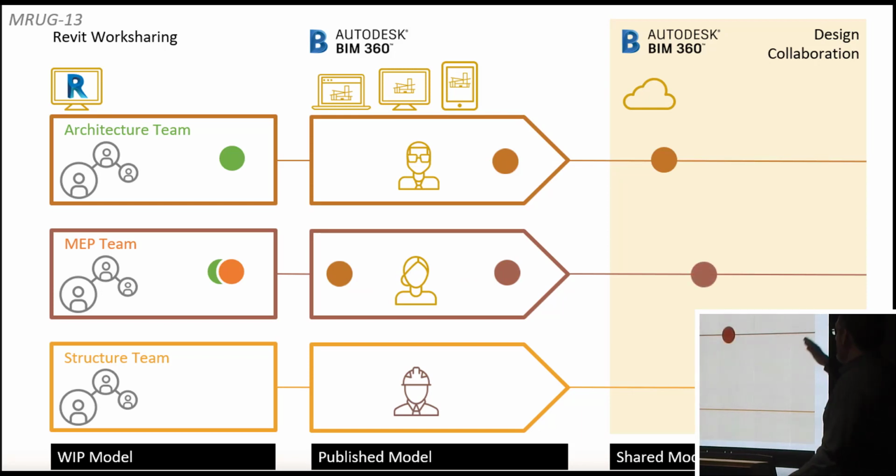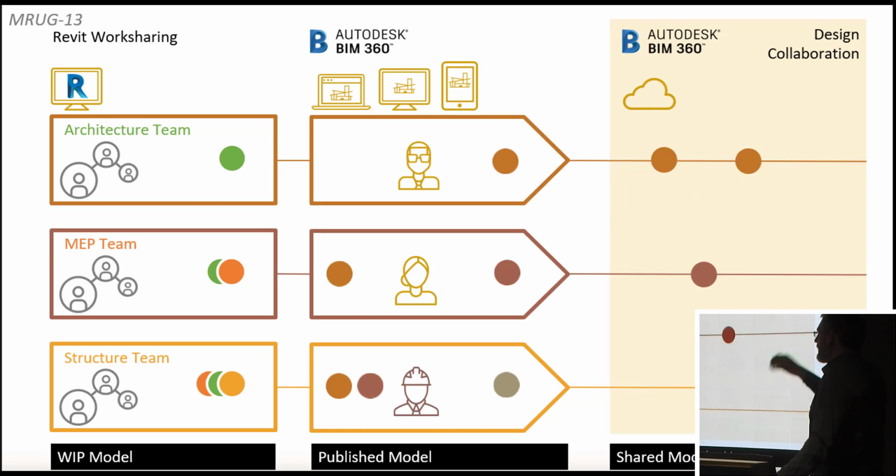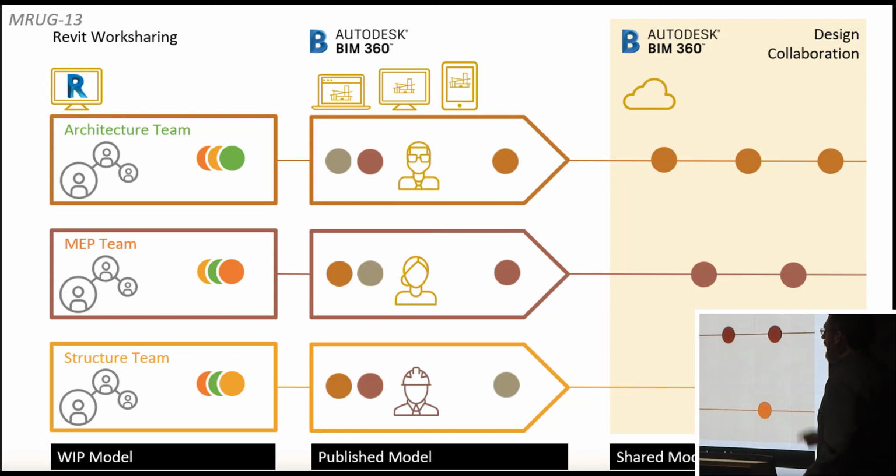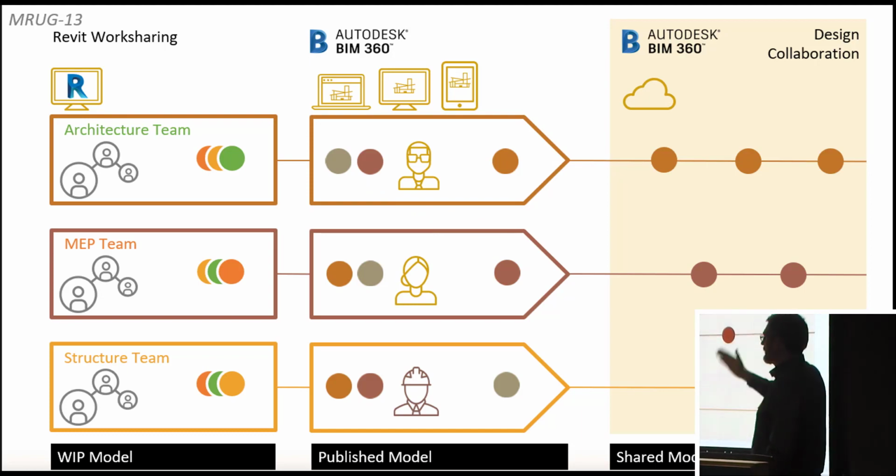So every time the file is pushed forward. Okay? The file is initially stored in the BIM 360 docs area, but actually you're working in design collaboration to collaborate information. Okay? So you're linking the information in the cloud, not locally on your own server. As you go through, and you see here, the project will just continue as everyone starts pushing back the data between the organisations. And then they'll link it into their own information as it goes through.